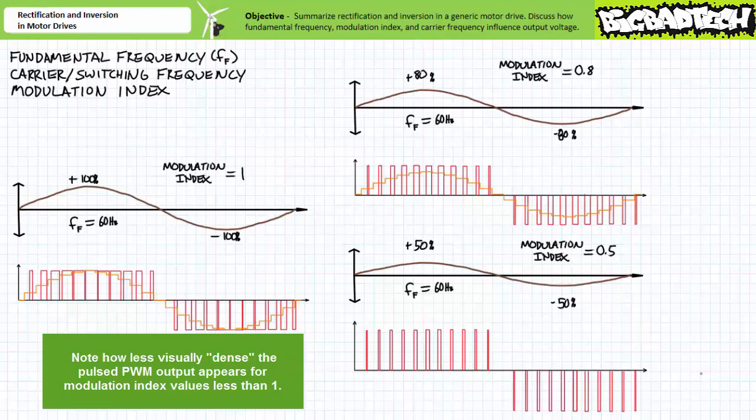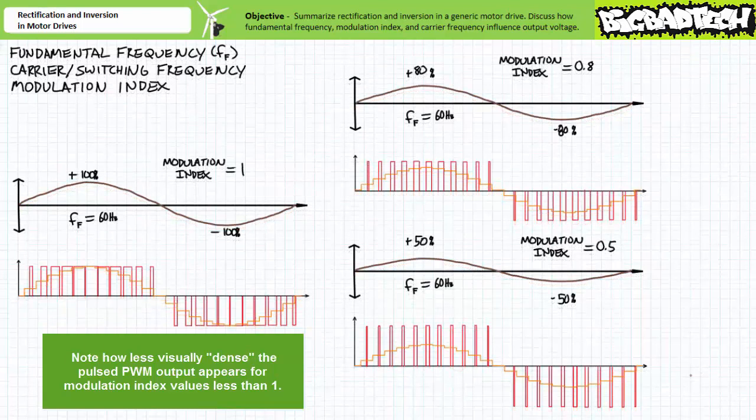The section centered at 15 degrees would have a median value of 0.13 of peak value. The section centered at 30 degrees would have a median value of 0.25 of peak value. The section centered at 45 degrees would have a median value of 0.35 of peak value, and so on. As previously, given duty cycle for a particular section still influences the average for that particular section, and the fact that duty cycle has been dialed down to a maximum of 50%, the output is proportionally reduced to 50% of maximum.